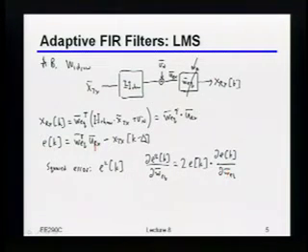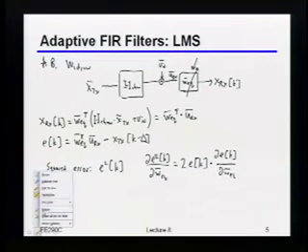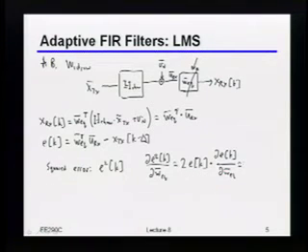Yeah, it's just u_RX. Because if I take the derivative of this with respect to the equalizer, my transmitted bits hopefully have absolutely nothing to do with my equalizer coefficients. So when I take the derivative, that just falls out, and all I'm left with is whatever my equalizer coefficients were in the first place. So in other words, my derivative is just going to be equal to 2e of k times u_RX of k. And again, I'm using a vector here because this means that it's the derivative with respect to each one of those individual coefficients.